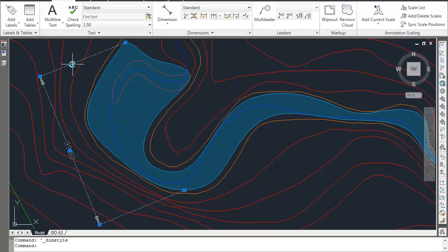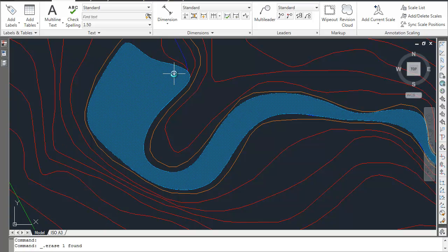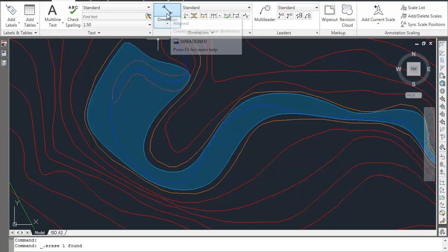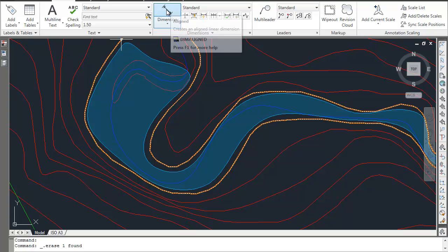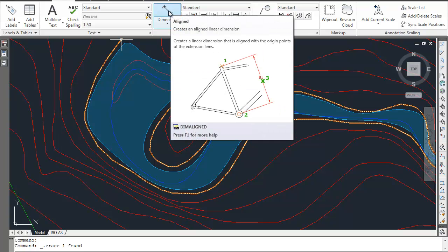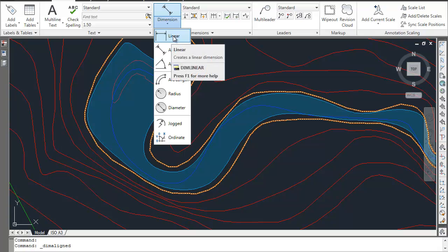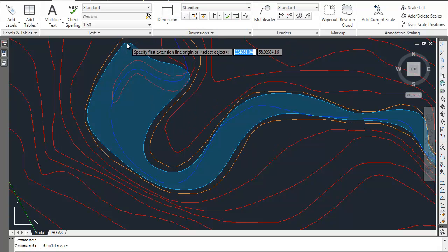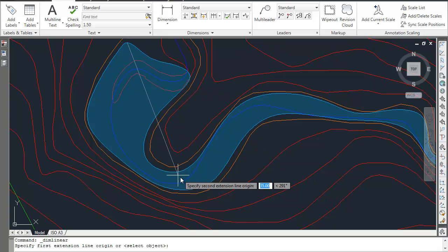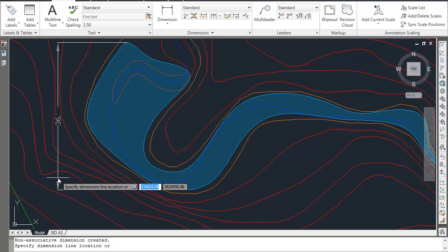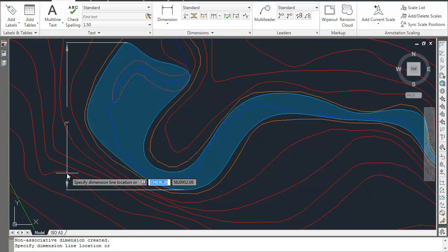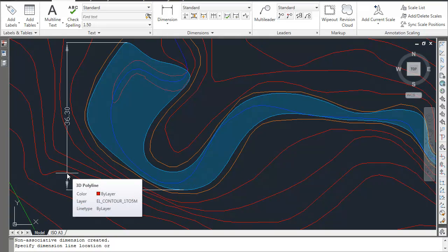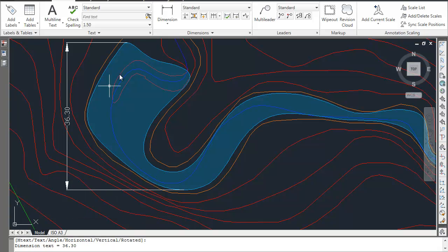Now that we've changed it, I'm going to just delete that. Okay, and I'm going to add the new measurements in, but as you can see they're all white. Oh no, I'll just add them here. So dimensions, and this time we're going to do our linear units. Now what I'm going to do with this one is click on the highest point, I'm going to click on the lowest point over here, and when you drag out, you'll notice that it drags out as the width of those 2 points, not the distance between those 2 points. Okay, that will apply it.